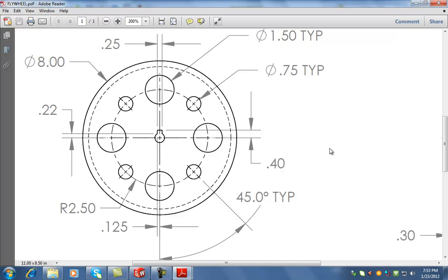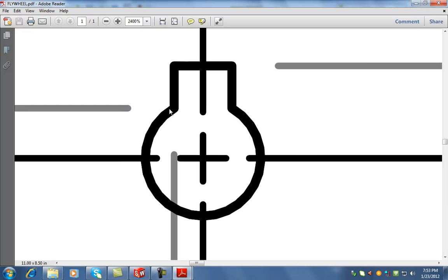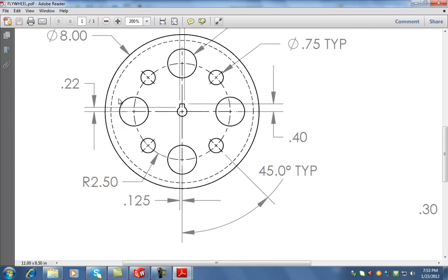Nope. I don't actually give you the diameter. What I give you, the 0.22, is actually the distance from the x-axis to the bottom of this rectangle. The circle keeps going up. So that's not really the radius. I give you the distance to the bottom of the rectangle. But using those distances, the 0.22 and the 0.4, you should be able to make the sketch fully defined. Do not pick the size of the radius to be 0.22. If you do that, this will not fit in the crankshaft, and when we try to assemble it, it will cause trouble.